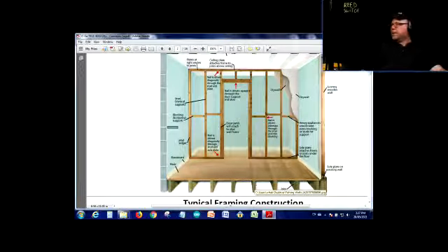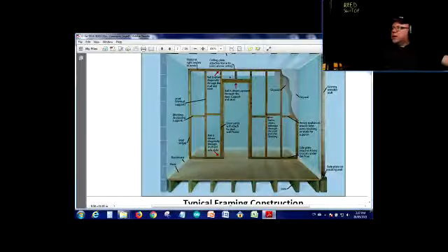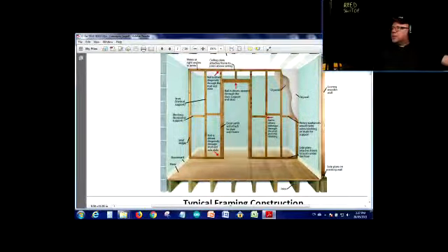So that's as far as it goes. You've got to watch if there's a dividing wall. Yes, you're going to have a hollow space here, but you have to make sure there will be horizontal studs or noggings. And of course, when it comes to framing around the doors or windows, you're going to have some extra timber to come across. So the best thing is to run the wires before the drywall goes in.